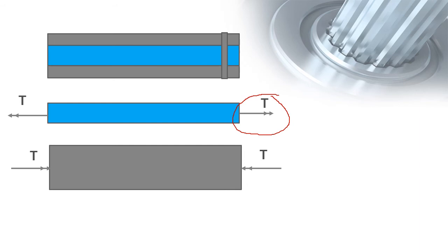When we draw the FBD of the pin, we have the clockwise torque from the steel shaft because it wants to go back to its original position. And we have the counterclockwise torque from the aluminum shaft. Again, note the law of action and reaction. We have the diagram of the steel shaft and the diagram of the pin. The torques should have opposite directions.